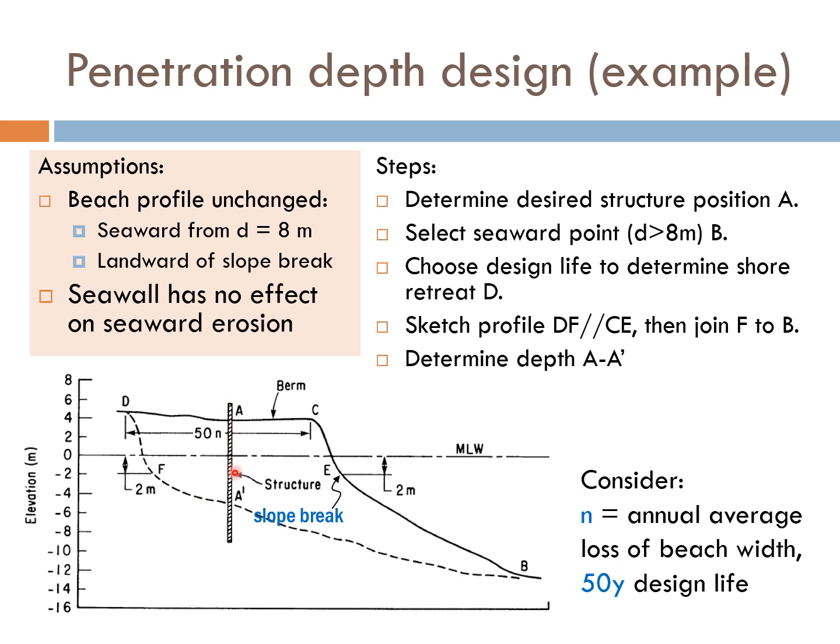And since this structure will not have any effect on the erosion on the sea side, we expect this beach profile to be eroded over the 50-year period and eventually form this beach profile over here. But due to the presence of this seawall on the land side, this part of the beach will not be eroded under the protection of this seawall.